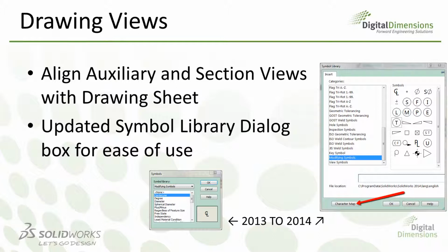For example, the ohm symbol, if you're doing an electrical schematic, you can find the ohm symbol within Windows Character Map. So for those of you that have seen my tech tip under DDiCAD.com/tech center, you know that you can go into that character map, select the special character that you want to use, copy that to the clipboard, and then simply insert it into your note.